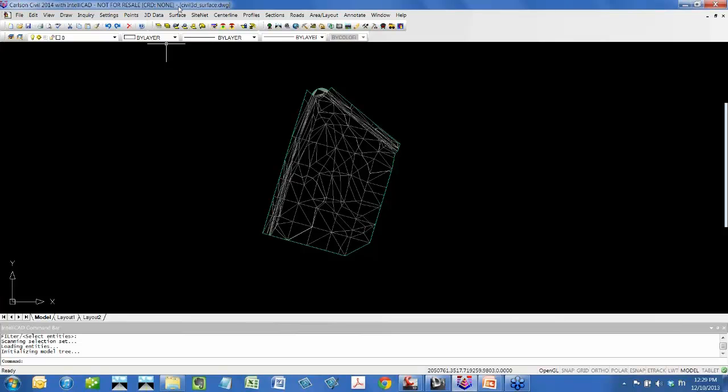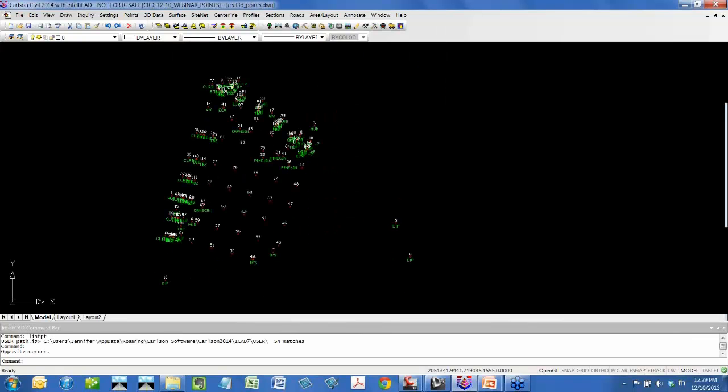And then the other question, when the points are created in Carlson, will they have the same point numbers and descriptions as they had in Civil 3D? Just on the conversion? Or was that from Land XML? I think the conversion did, because it has the point numbers and descriptions there, so it's just using the same values. If no descriptions are listed, then they won't come through. Correct. I think that's something I've emailed in to Carlson Tech Support on, to find out if there's anything you can do to drag that data out of Civil 3D if it wasn't in the drawing.